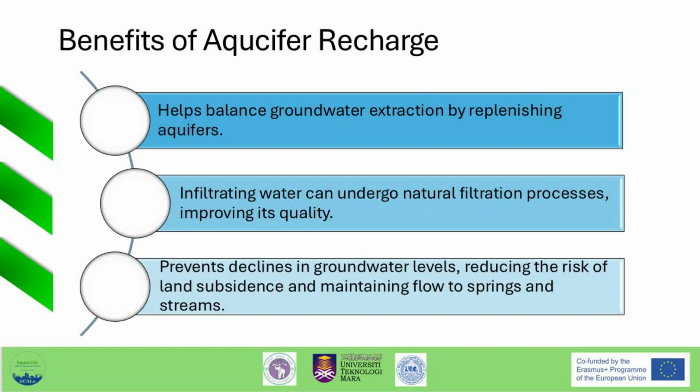The benefits of aquifer recharge pertain to three aspects. It helps balance groundwater extraction by replenishing aquifers. Infiltrating water can undergo natural filtration processes, improving its quality. Lastly, it prevents declines in groundwater levels, reducing the risk of land subsidence and maintaining flow to springs and streams.